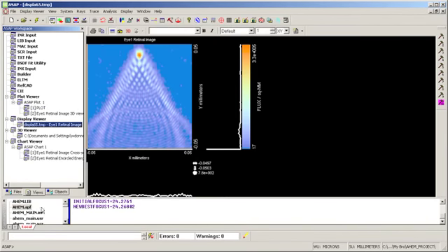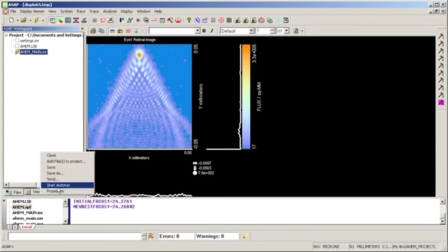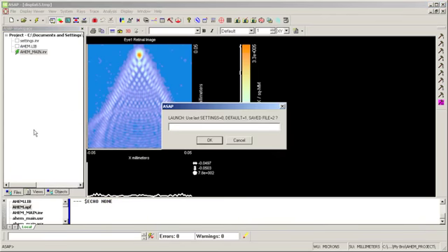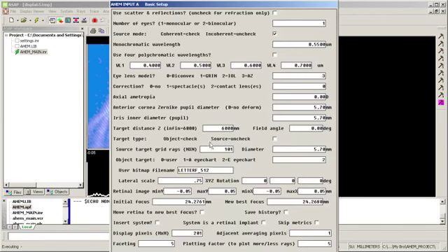So in order to do this, I go and load my coma aberration. So I have a saved settings file. Say OK. All right, so I've got a coherent mode as well now, so I have that box checked. I've got an anterior corneal Zernike pupil diameter of 5.7, which is the same as the pupil of the iris. So I'm going to deform over that cornea with some coma.